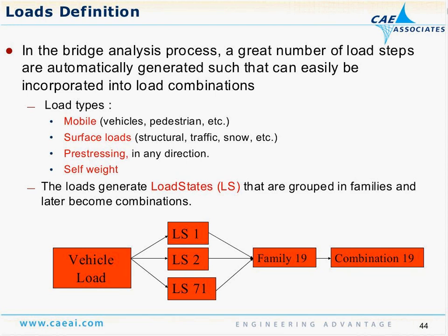based on code definitions. And so it can allow you, very fast and efficiently, to define a very large number of different loading conditions. These loading conditions are analyzed individually but can be grouped into different families, and the reason for grouping into families is for the load combination capabilities within CivilFEM. So, for example, if I want to run a case where I take one of the worst case scenarios of that group of loads, then I'll select from the family of the various independent loads and tell CivilFEM, select me the worst case scenario from that group.